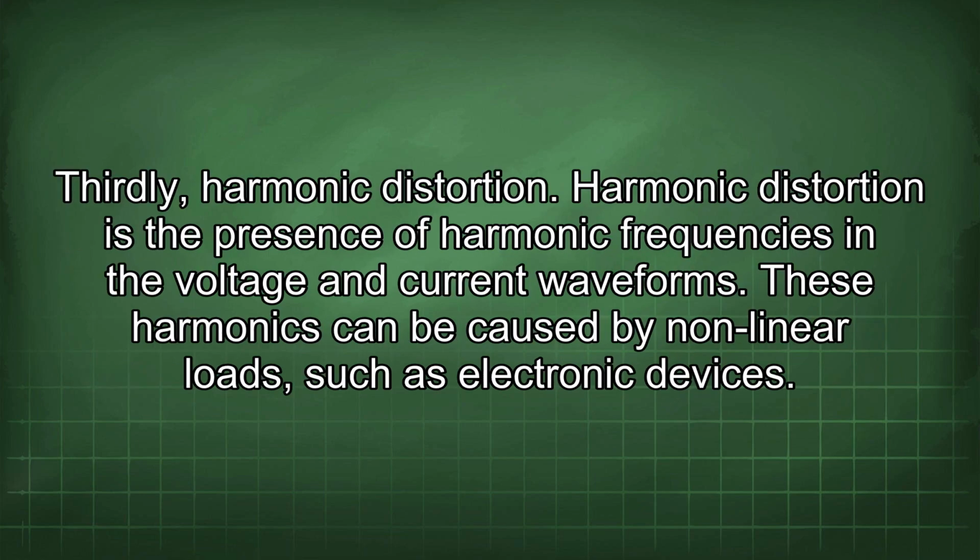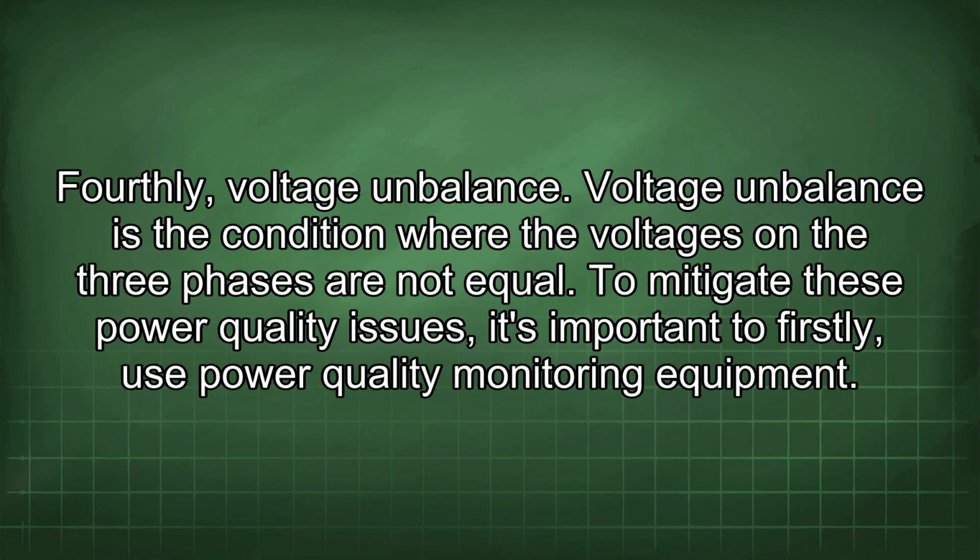Thirdly, harmonic distortion. Harmonic distortion is the presence of harmonic frequencies in the voltage and current waveforms. These harmonics can be caused by nonlinear loads such as electronic devices. Fourthly, voltage imbalance. Voltage imbalance is the condition where the voltages on the three phases are not equal.